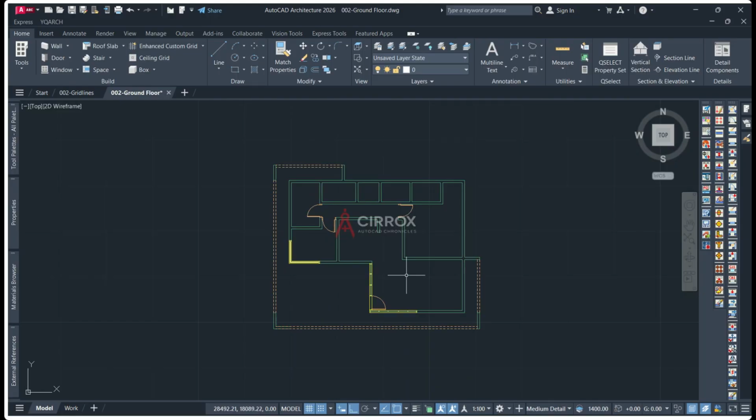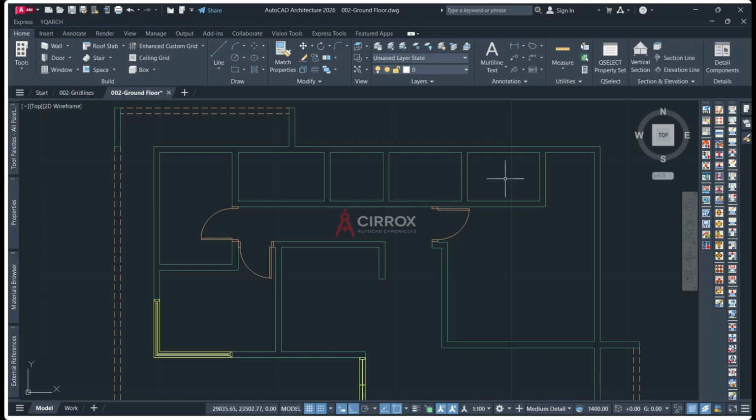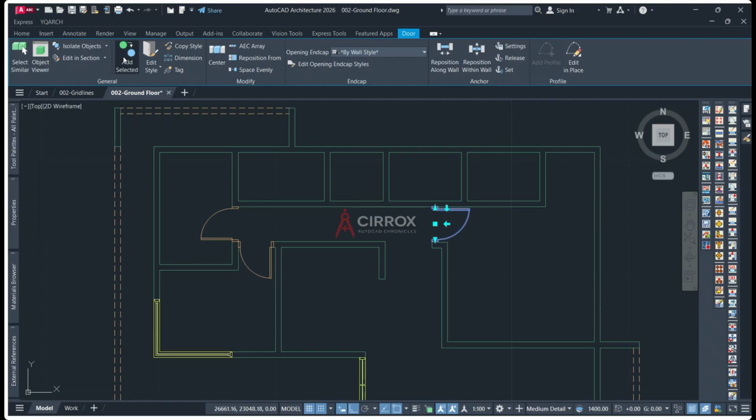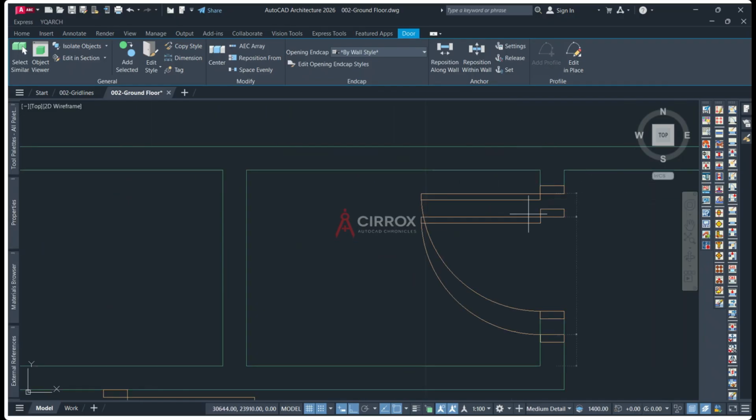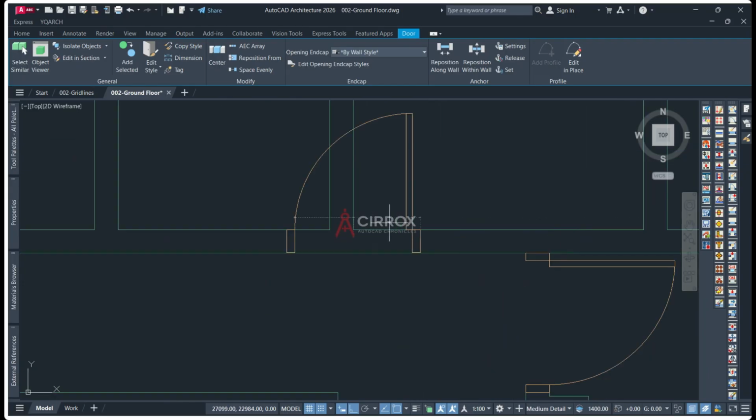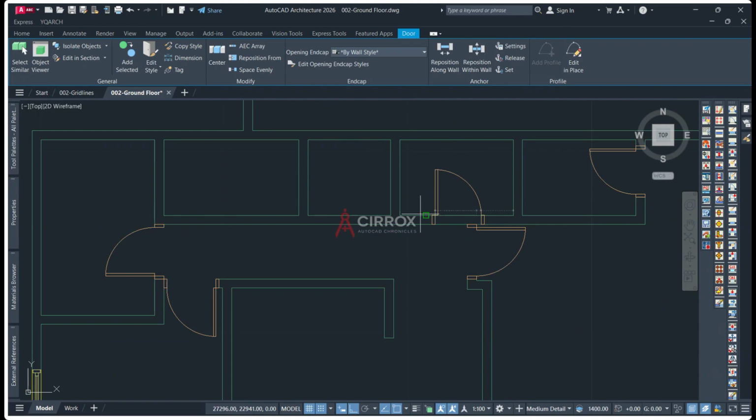Okay, so now that our doors have been fixed, we can now go on to add the rest of the doors too. There's a door here. This is a washroom, this is also a washroom. So I selected, but this time I'm going to be 750. So 750, and come here and I'll put it here, and also come here and put in this door, because there is a door here too. Okay, all right.